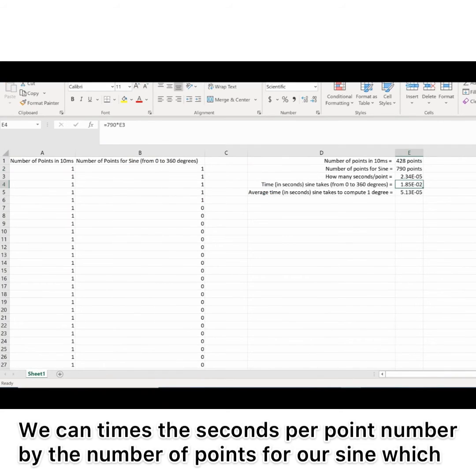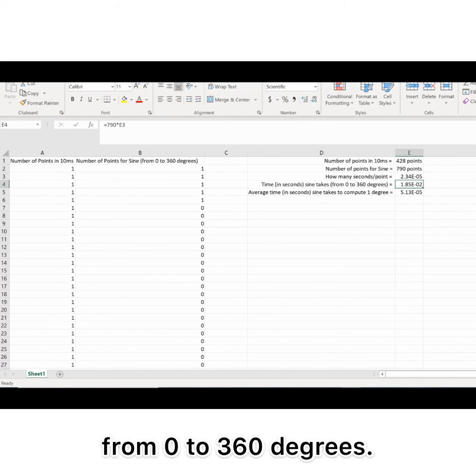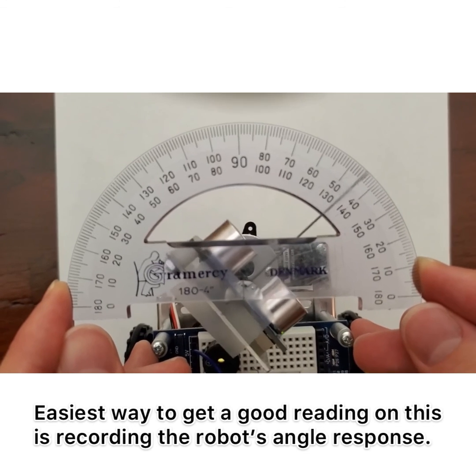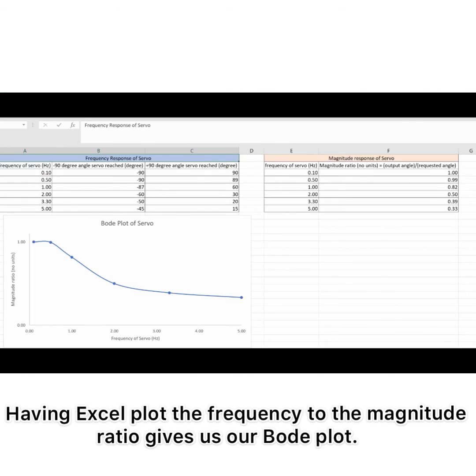We can multiply the seconds per point number by the number of points for a sine, which is 790, and that'll give us the total amount of time that it took the sine function to go from 0 to 360 degrees. The easiest way to get a good reading on this is recording the robot's angle response. Having Excel plot the frequency to the magnitude ratio gives us our bode plot.